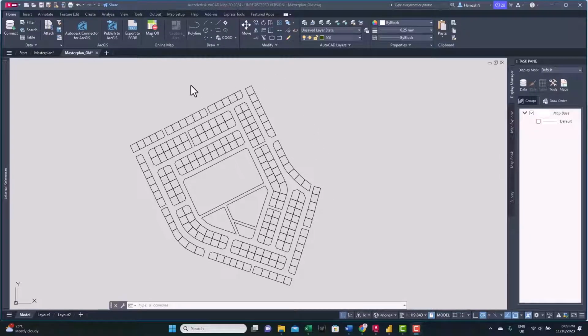So this is a master plan CAD drawing we want to visualize inside Power BI. We have different housing plots and we want to be able to analyze and search this master plan in Power BI and find out, for example, which plots are single row like those. And in a minute we'll see that we have a sea here, so we'll see the plots having direct access to the sea here, which ones have a garden view, what are the different areas for the plots, and so on. So the first thing we want to be able to do is to export these plots in GIS format